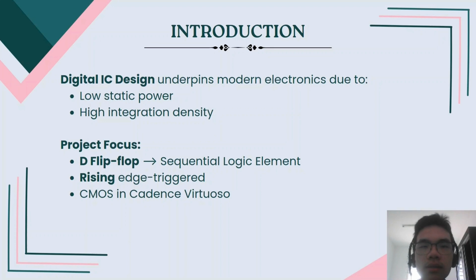So this project focuses on the design of a D flip-flop, which is a key sequential logic element that captures and holds data on the rising edge of a clock signal. This entire design, from schematic to simulations, was carried out at the transistor level using CMOS technology in Cadence Virtuoso.